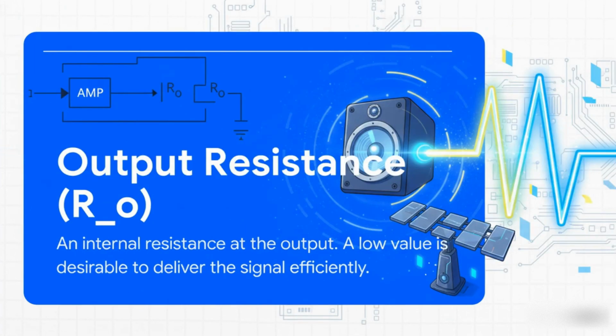And finally, number 3 is output resistance. Think of this as a little bit of internal resistance, like a hurdle the newly amplified signal has to jump over on its way out the door. Now, if you want to deliver that powerful new signal to the next thing in the circuit, say a speaker, you want that hurdle to be as small as possible. A low output resistance means a signal gets out easily and efficiently.